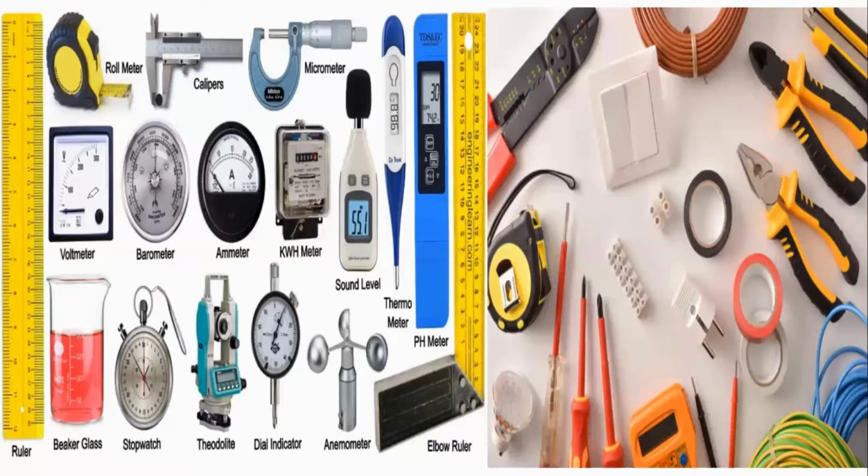Okay, now this voltmeter, ammeter are nowadays we don't use separately because we use multimeter, because ammeter and voltmeter is already there. But please remember, when we talk about ampere meter in multimeter, you cannot check AC. AC option is usually not given. For that, you need to check the clamp meter. That we will discuss a little later. Okay, I hope you understood this slide.